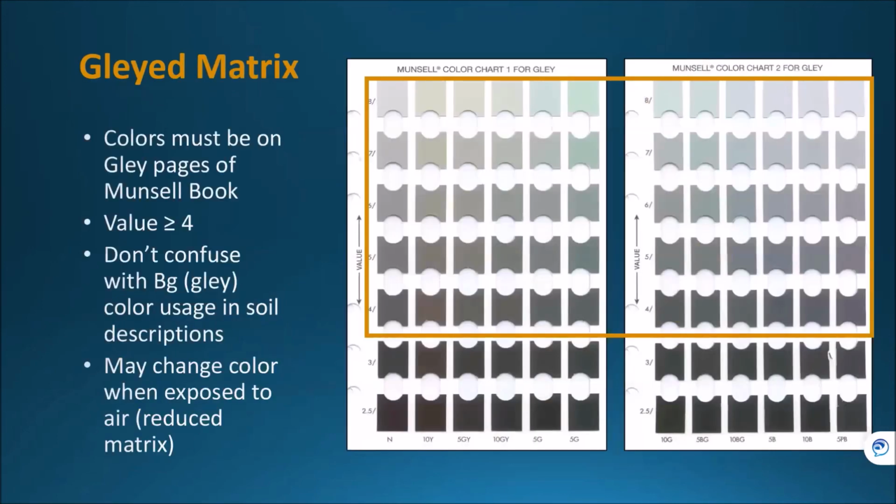These are just a couple of other pages. These are the Gley pages that you might see in the Munsell color book. I always just refer to these as the bottom of the pond mud colors. If you've got these kinds of really grays to greens or different types of bluish colors, then the site's probably been pretty historically wet in the past. That's usually a good indicator.